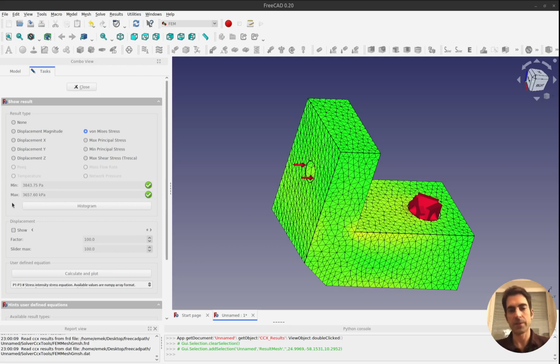so this is around 3.6 megapascal. The type of wood that we have depends on, of course, whether you are using oak, timber, or what kind of wood material you use. If we have this technical detail, then we can also know the maximum stress which is allowed in this material, and then we can say, yeah, maybe this is too much. Then we can change the design or change the force.